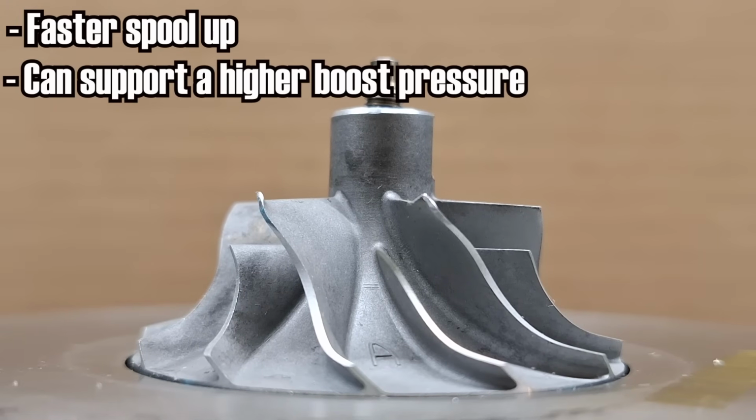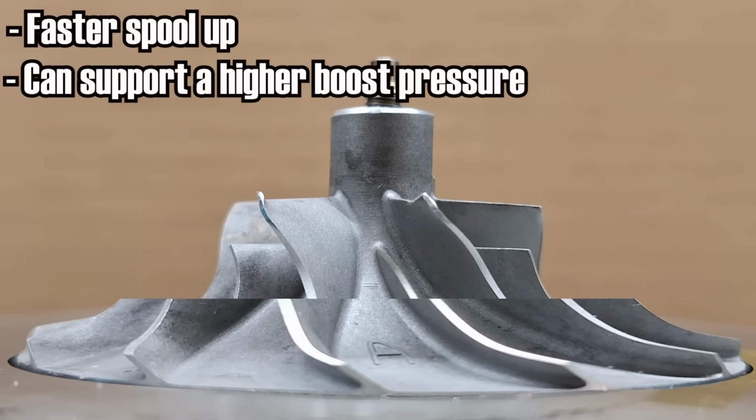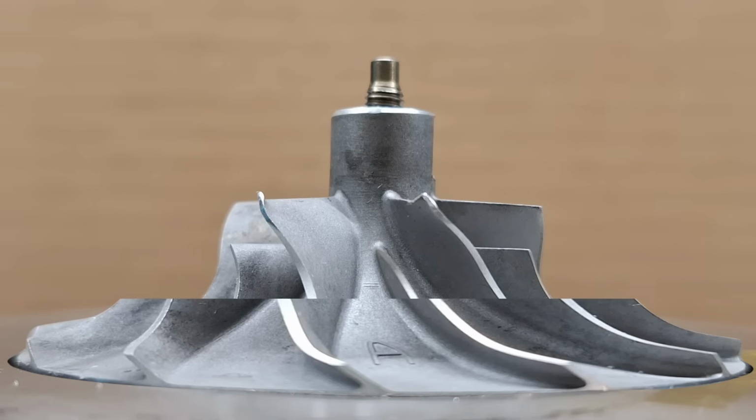But note that these effects of an increased exducer diameter have diminishing returns, so don't expect to see something like this on a turbo. This would just be very heavy and would have massive boost lag.